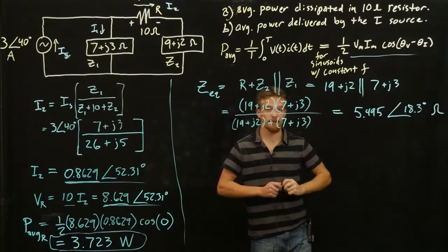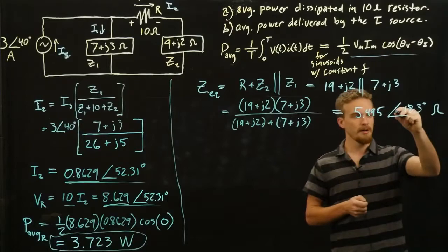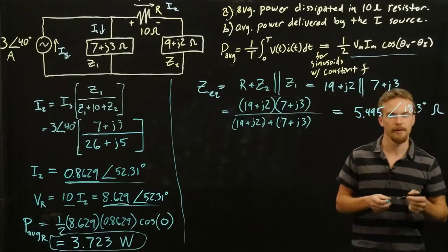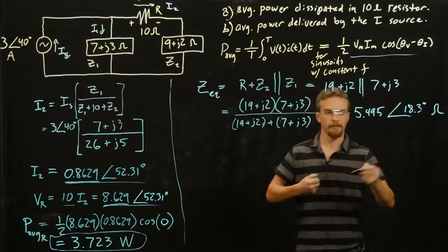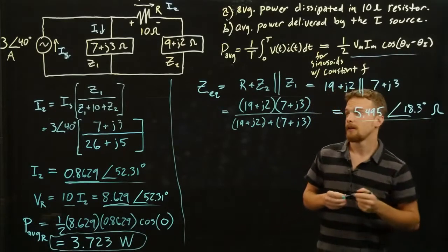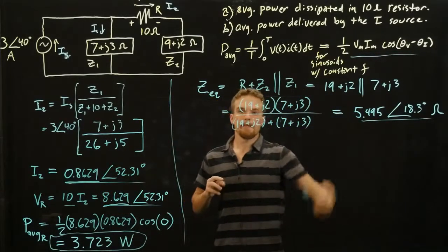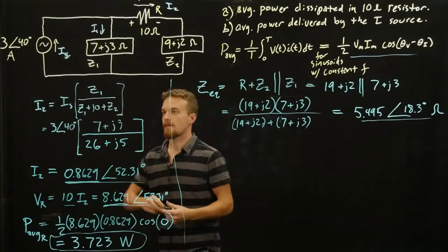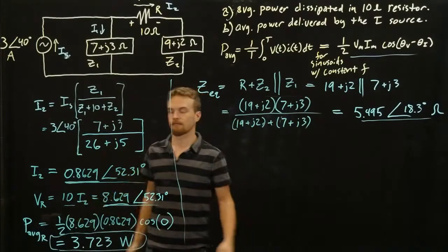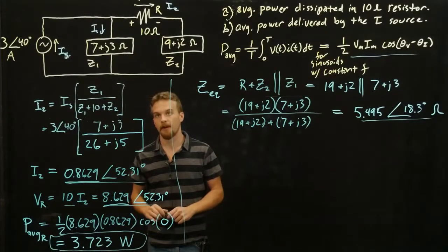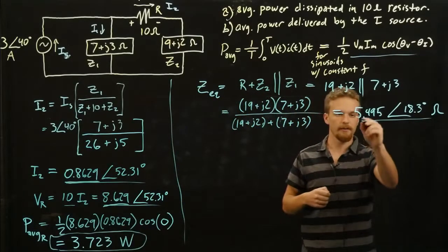So we have a complex valued impedance, right? In the real imaginary plane, it's at an angle, so that means it has an imaginary part. But that's okay. We're used to dealing with that. So that is saying that this circuit is equivalent to this source with just one impedance at that value. So if we had that, how did we get the voltage across it? We could just multiply the current value by this impedance value.